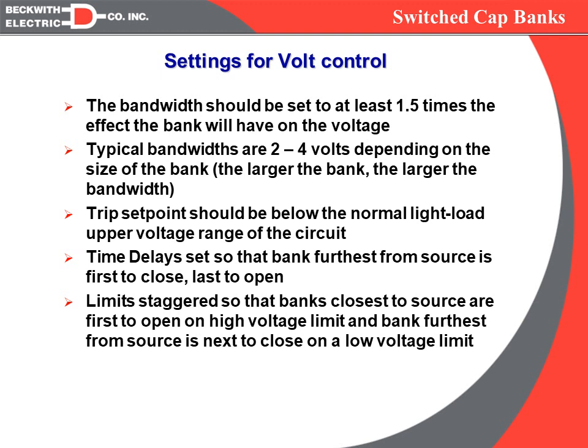So now the settings for the voltage controls. Obviously for capacitor banks, we said that we want the cap bank furthest to be the first to close and the last to open. Therefore, we need to have two separate time delays, one for open and one for close. And we also want the time delays on our caps to be shorter than our regs.